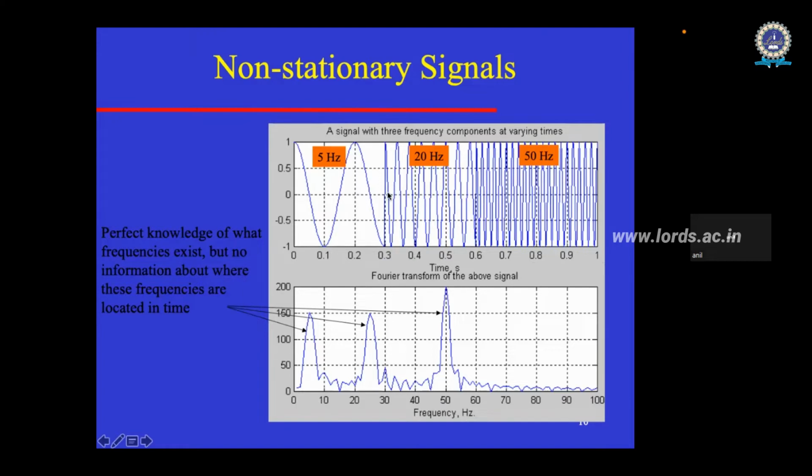So that is not the right spectrum, but at the same time that is not wrong also, because the window size decides everything. So we have to decide the window size. Unfortunately, in a non-stationary signal, you see this signal and you may say that a window of 0.3 or 0.2 is not good, take 0.1. That may be a good window.